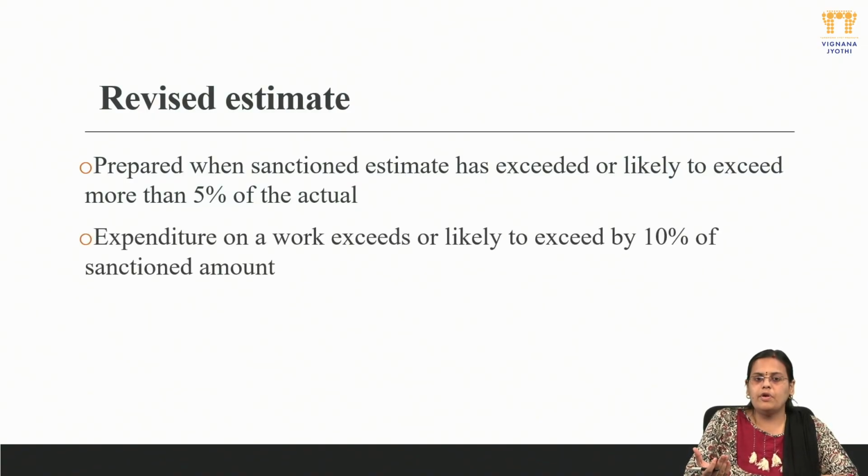Sometimes even if you use the same materials, due to difficulty at the construction site, your expenditures on your work may exceed by 10%. Then also you can go for revised estimate. If it is more than 10%, actually you have to go for revised estimate.